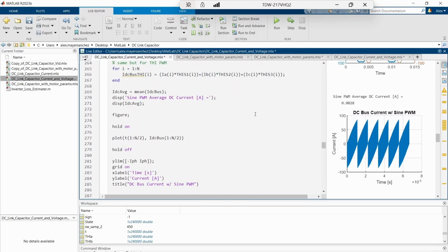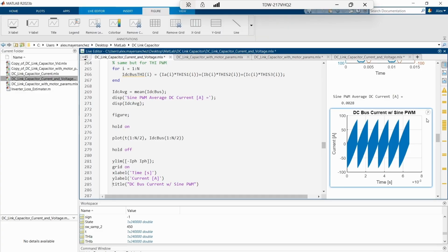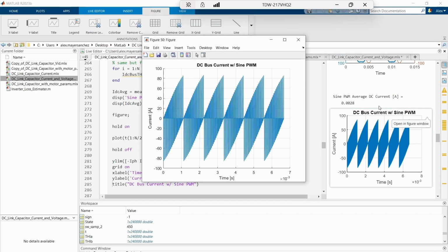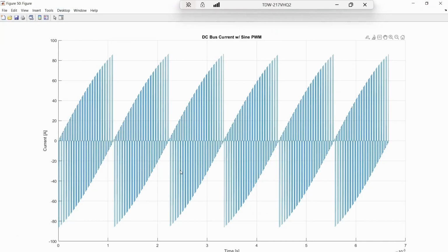And when we look at the DC current in, we get 0 current in because we have 700 volts on the DC link, but the power factor on the output is 0, so the power in needs to equal 0, so 0 times 700 equals 0. So now you can see that the current is always going in and out, but it's always an average of 0.